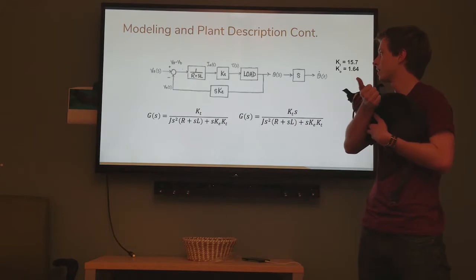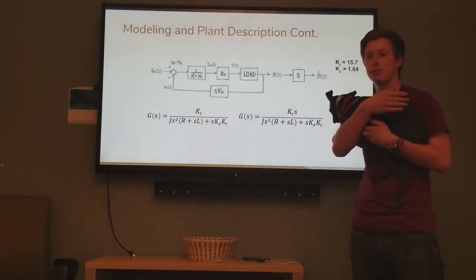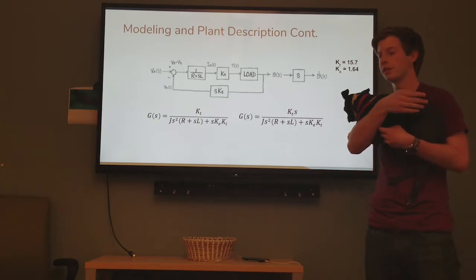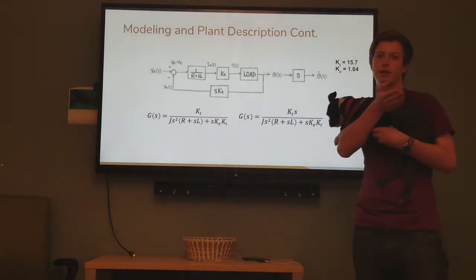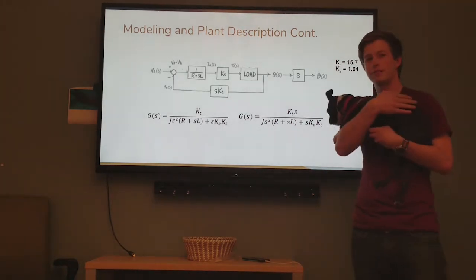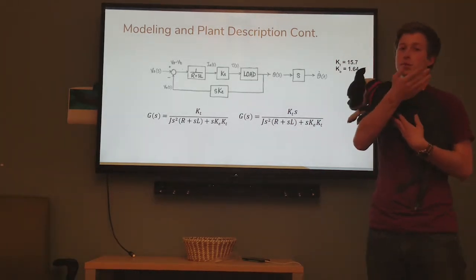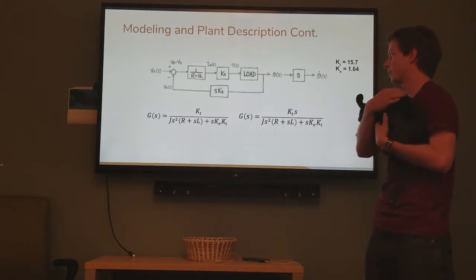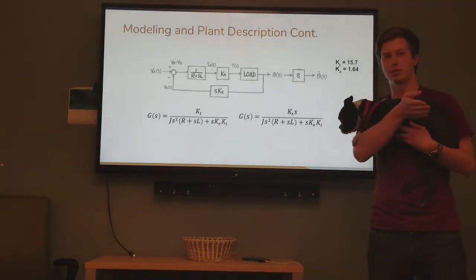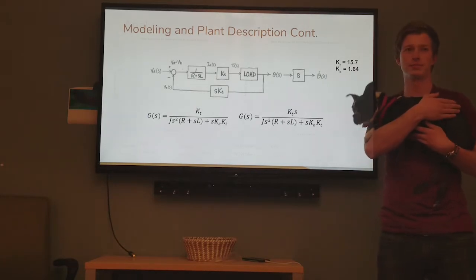And by also adding an s to this transfer function, we could turn the output from being angular position to angular velocity. As a result, simplifying these two gets us the transfer functions below, where the first one on the left is the voltage versus positional output, and the one on the right is the transfer function for voltage versus angular velocity output.